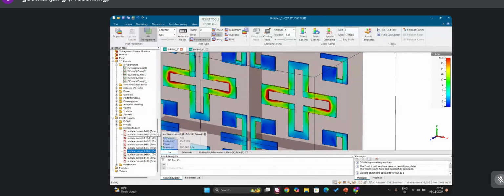It is a major advantage of designing independent resonators for band stop, and it is also applicable for band pass FSS. By designing these independent frequencies, you can achieve the frequencies without any mutual coupling. The main disadvantage I can say here is that you have to go for a little bit larger FSS. It is 2.3 here; you have to go for 2.5 or maybe 3 to achieve the independent frequencies.